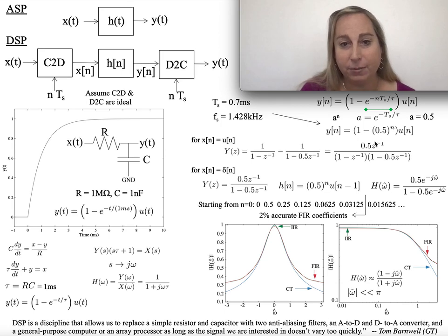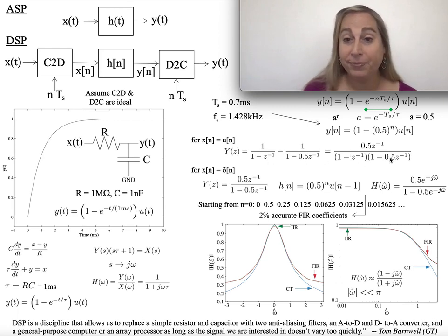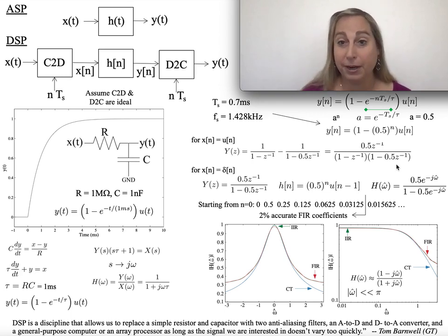And in fact, I can even say, well, what would that z transform have been, which gives me an underlying idea of what the structure would be underneath. What I find out of the z transform is that y sub n now gives me the subtraction of these two things, cross multiplied through, and I get 0.5 z to the minus 1 over the product of two terms. Cool, right? So from this, I could figure out what my difference equation is, which would be a second order. It's an IIR response, but that's the kind of response I would see here.